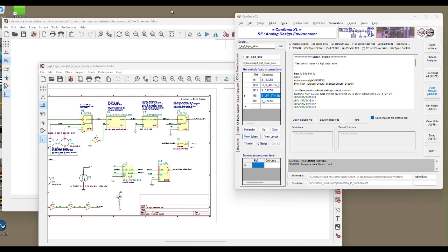NG Spice is a popular one, as is Xyce from Sandia National Labs. That works very well. There are some paid SPICE simulators that are modest cost. TopSpice works very well. That's one of my favorites. There's also waveform processors, things like that. These tools can all be plugged into the Confirma framework. So you can plug different tools in, but the framework and the flow change very little.